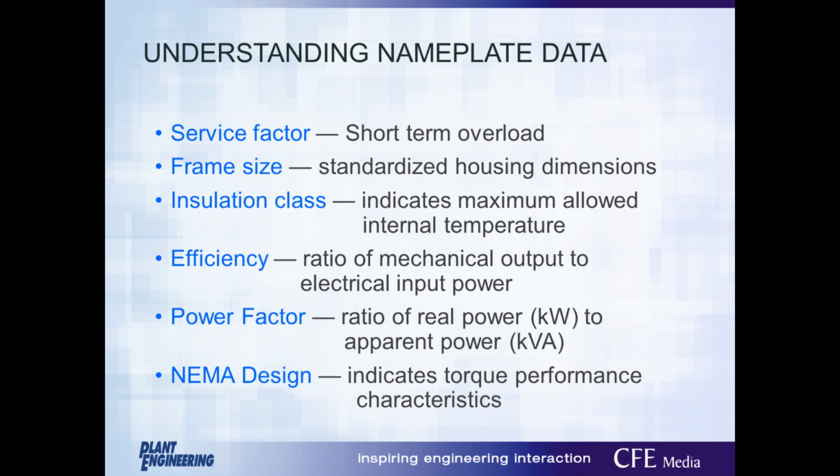Here are a few more parameters that you might find on the nameplate, including service factor, also called short-term overload factor, frame size, which is generally standardized across the motor industry, insulation class, which indicates the maximum allowable internal temperature, the full load running efficiency, the power factor, which generally is a ratio of real power used to total power generated by the utility, and then finally NEMA design letter.